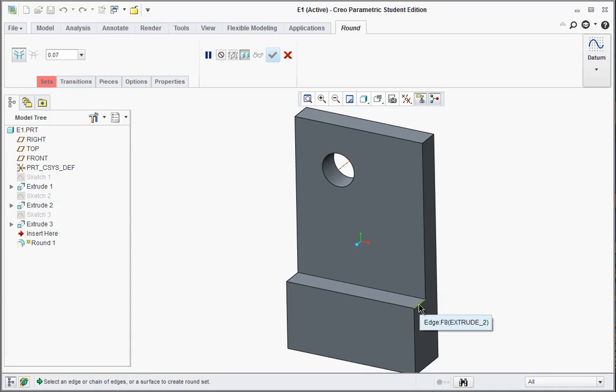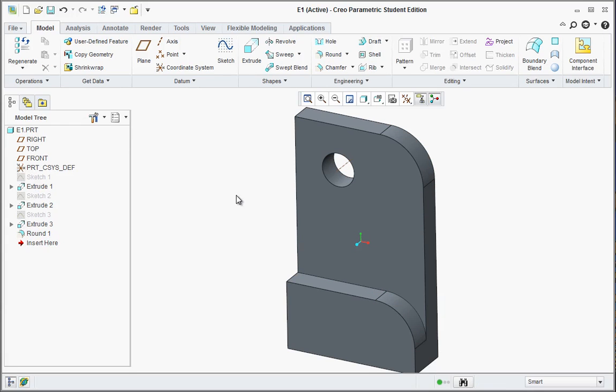There's a radius. Click on this edge here, and you'll see you'll get two little white handles that turn black when you grip them. Drag with the left mouse button to press, and you can put in radiuses. And you can change or double click on these dimensions to put in explicit values and update them. Hit the green check mark.